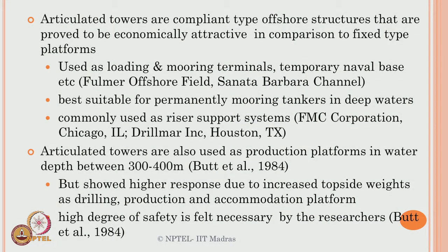And we all know that ATs are compliant offshore structures which are proved to be economically attractive for medium water depths compared to fixed type, because we started from fixed type. They can be used as loading and mooring terminals, temporary naval base. The classical application examples are the Fulmar offshore field and the Santa Barbara channel. It is best suited for permanently mooring tankers in deep waters. Even today they have been used. They have been commonly used most importantly for riser support systems.